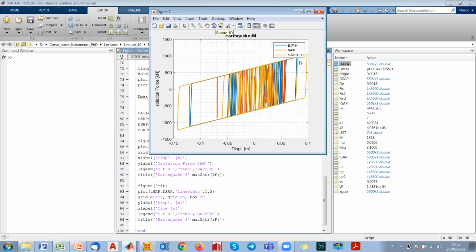And that difference is bigger for more flexible structures. Yeah, exactly. Because as soon as you consider more rigid structures, you get close to the assumption of a single degree of freedom oscillator. So as the fixed base period of the building increases, this means that the overall flexibility increases, so the stiffness decreases. We can say it in both cases. And so we are expecting some additional discrepancies between the two strategies. But if you consider an infinitely rigid structure, you are very close to what happens when you consider just a single degree of freedom. Thank you. Perfect. You're welcome.